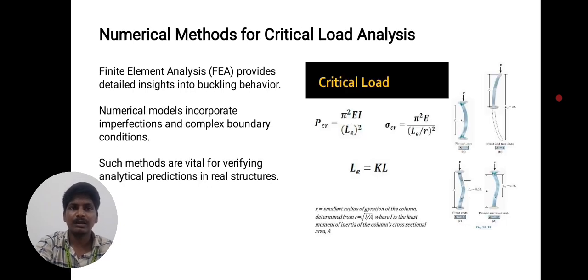Numerical methods for critical load analysis. Finite element analysis provides detailed insights into buckling behavior. Numerical models incorporate imperfections and complex boundary conditions. Such methods are vital for verifying analytical predictions in real structures. These are also critical loads, pi squared EI by L_e whole squared.